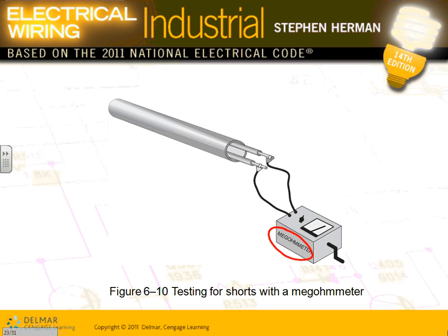Before, in major feeders, guys, before you energize and blow up a switchgear or burn equipment, they have a megohm meter. They pump voltage across conductors, phase A and phase B, and this should show infinity, meaning they're not touching each other. They call it continuity testing.